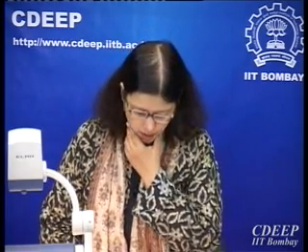And one more thing is, I don't think either Mentor or Cadence would be able to simulate AC response. Therefore, you need to get it at a few frequencies. That means you do transient analysis. In last semester, we did it using SPICE sequence. See, because when you want to use AC simulation, you need to sweep frequency and get the transfer function. But switch capacitors are